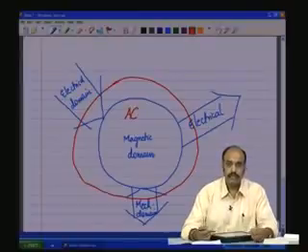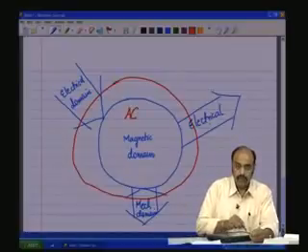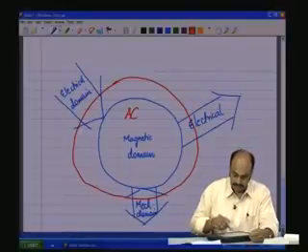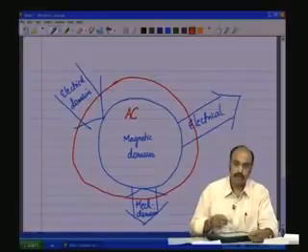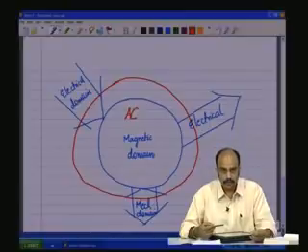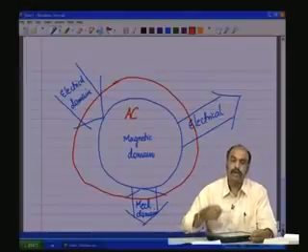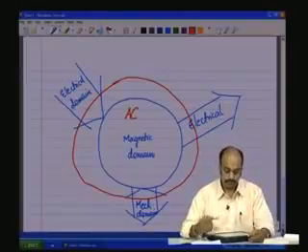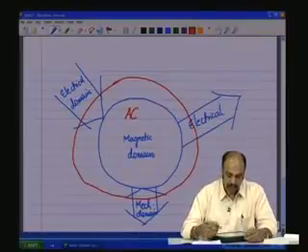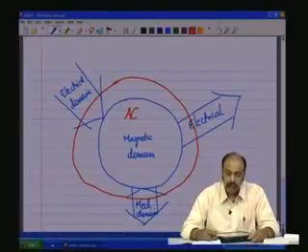In the case of the induction motor with shorted rotors, you have only one electric domain which is inputting, and this other electrical domain is not there, and you have the mechanical domain. In case of the wound rotor, where you have the rotor windings not shorted, taken out to a set of resistors, then you have the input electrical domain and output electrical domain, you also have the mechanical domain, and so on and so forth. So, like that you can have many combinations, but all falling into this class or this type of concept.